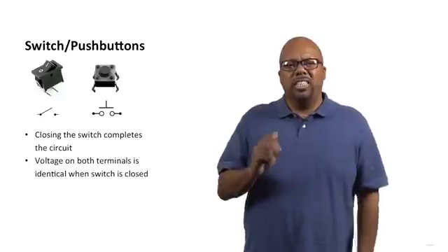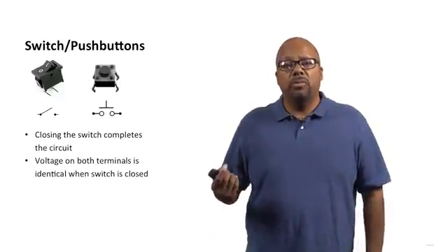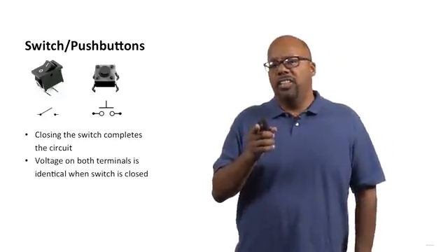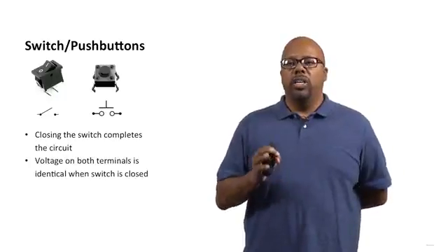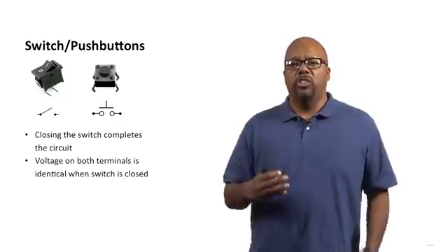Now, one note I should just bring up right now, the push button that we have there is actually very similar to the one you have in your kit. That thing has got 4 legs on it. It's hard to see. You can only see maybe 3 of them here, but there are 4 legs. So it doesn't really just have 2 terminals. This one has 4, but 2 of the terminals are connected to each other.